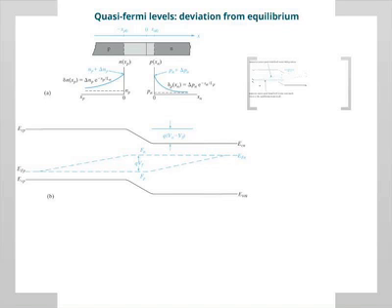And this difference between the quasi-Fermi levels is the applied voltage. Okay? Which intuitively should make sense to you because the applied voltage, remember, controls the injection of the carriers, right? And this difference when they split has to do with the excess carriers, excess minority carriers, right? You see that, right? So for instance, in the p-type, the original Fermi level starts going up because there are excess electrons here, right? And the maximum deviation happens right at the junction where you have the biggest voltage difference. You have the biggest injection of electrons.